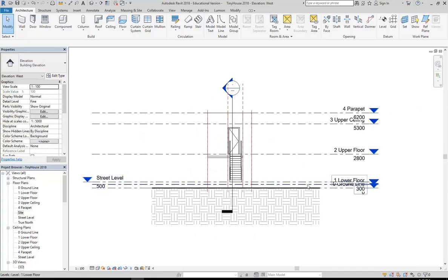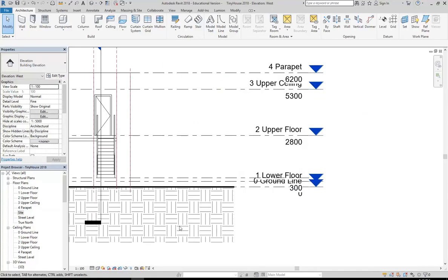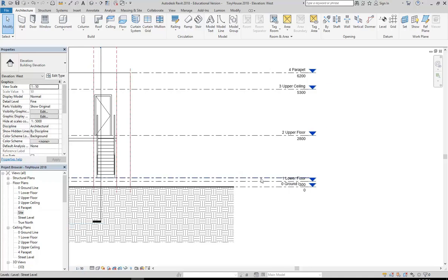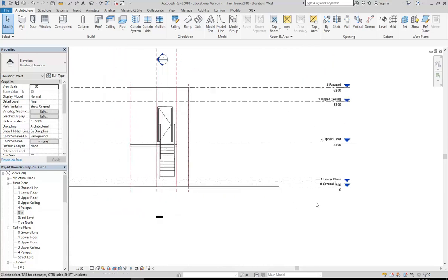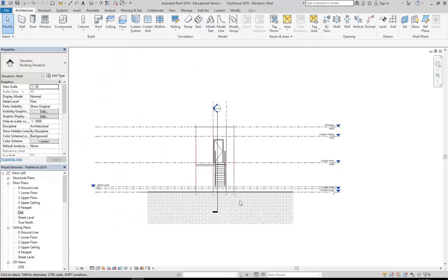And we can see that obviously there we can see these levels, but the text is fairly large. So if you remember that little trick I showed you before, change the scale. Yeah, so if I make it 1 to 50. Or even 1 to 20, well 1 to 50 is probably okay. So there we can see the different heights a little bit more clearly. If we go to 1 to 20, it would even be better, but we don't want to go too far with this.